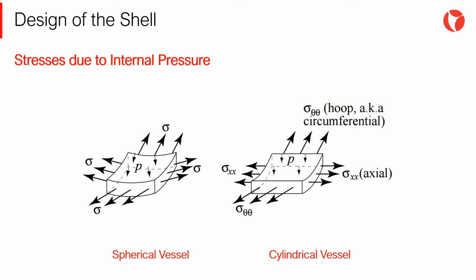That is why, for the same diameter and design conditions, the maximum normal stress in a spherical pressure vessel is 1/2 as large as that in a cylindrical one. Therefore, the wall thickness follows the same relationship. As previously mentioned, this means that a spherical vessel is the most structurally efficient. However, the cylindrical shape may be more convenient to fabricate and transport, among other things.